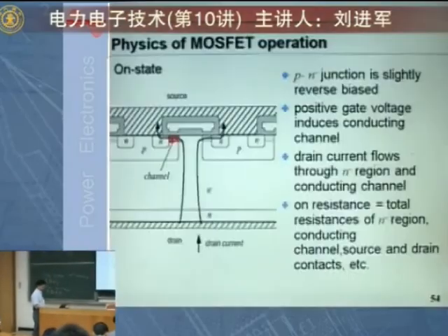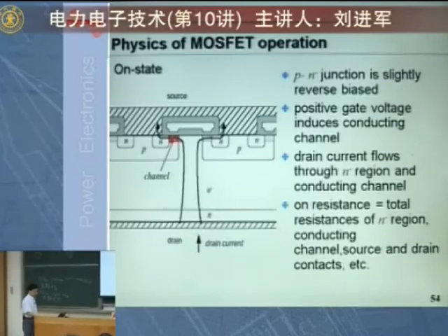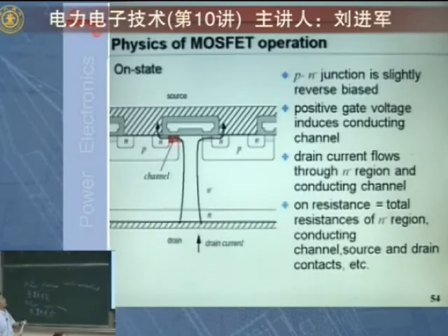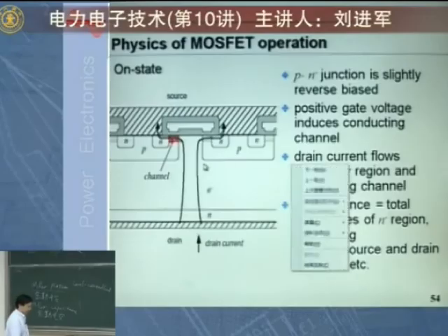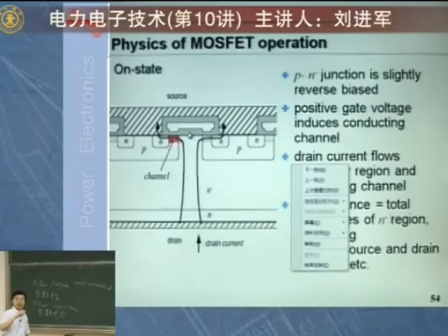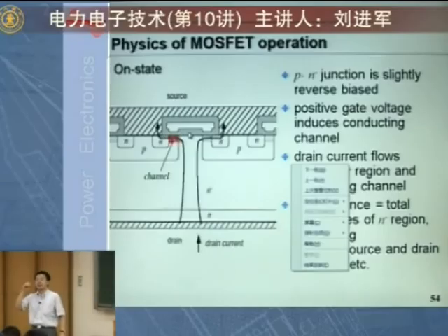If you look at the structure of this MOSFET, between gate and drain, you have a metal terminal here, and then you place these metal terminals in parallel. That, of course, will generate capacitance.